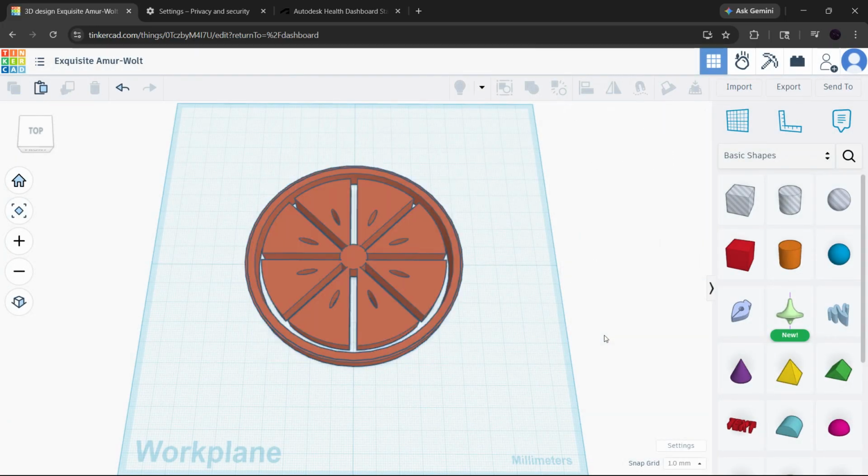So to quickly recap, simplify your model, regroup complex geometry, turn on hardware acceleration, test in incognito mode, clear cache and cookies, try exporting a selected shape or different file type, and check your network or server status. One of those fixes usually solves the Tinkercad download error.